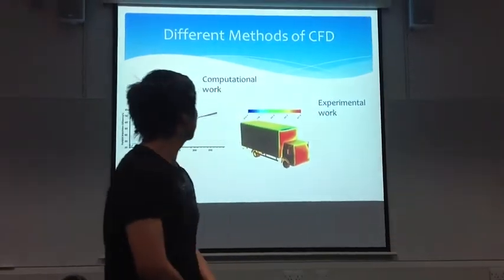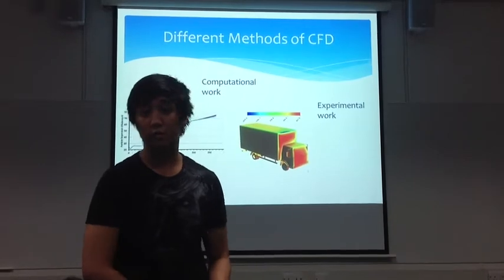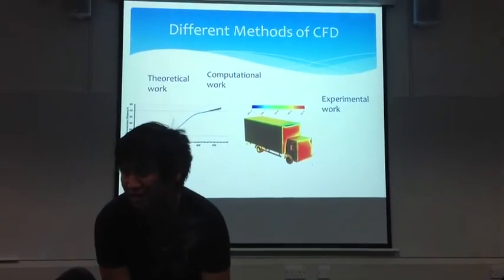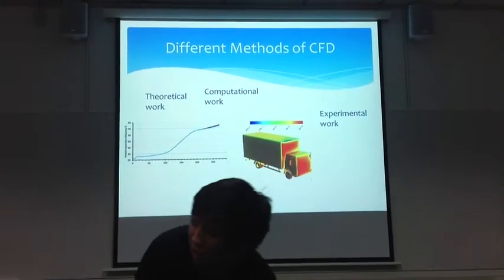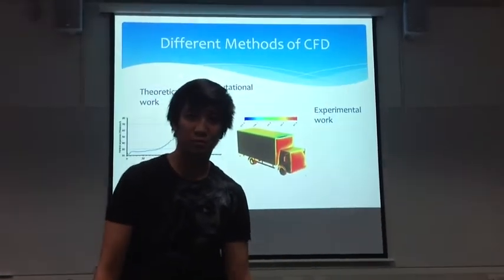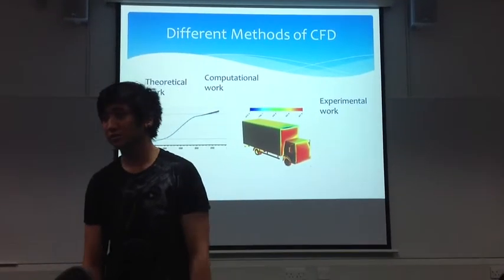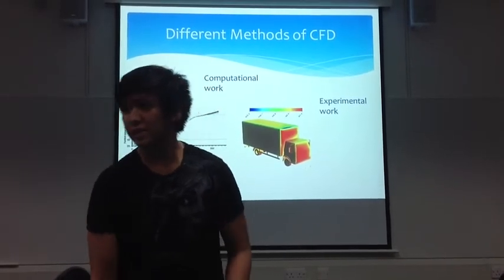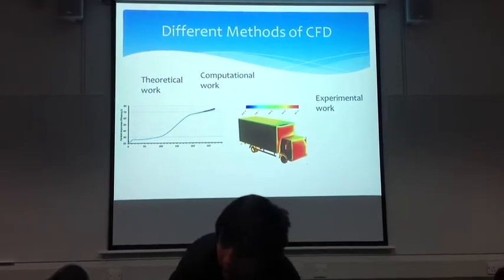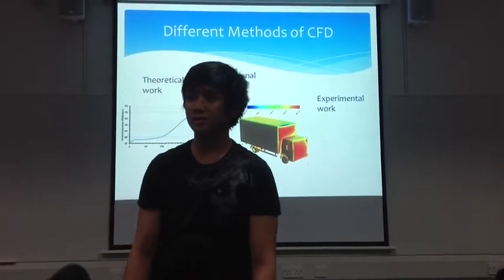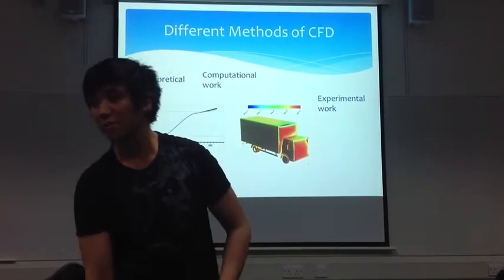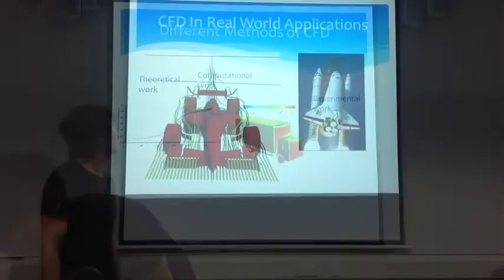CFD versus experimental CFD. The pros of using experimental CFD is that you have the possibility of a rapid turnaround, it's usually safe and less expensive, as you don't have to use different analysis. It's very detailed and has powerful visualization, and the cons are the modelling uncertainty. You get limited by available resources. It can be a problem with length, time, skills.